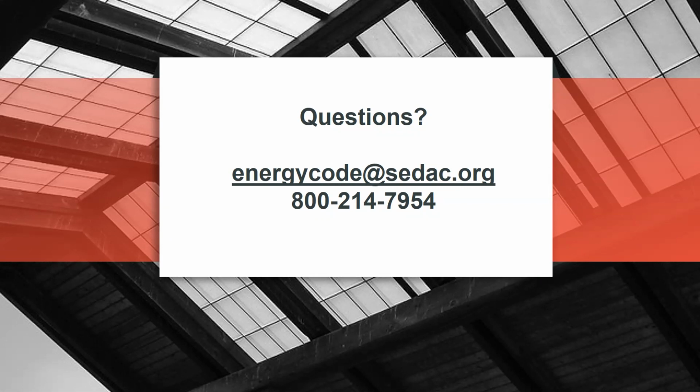If I recall, the requirement is 24 square feet of fenestration area in order to qualify as a day-lit zone or a side-lit day-lit zone. So yes, if your office only has a 4 by 5 foot window, you would be below that threshold, so you would not have a daylight zone in that office. Therefore, no daylight harvesting controls would be required for that.